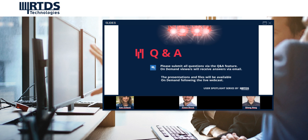The thing that I would pay attention to is the implementation of the protocol on the amplifier. You might run into some challenges if the implementation on the amplifier is not initialized properly, as well as having to look at the data point mapping between the model and RTDS and how it's defined on the amplifier side. But I think the fact that there's a limited number of amplifiers, or the ones that are most commonly used, there's a close relationship between suppliers and RTDS in order to iron out any issues.